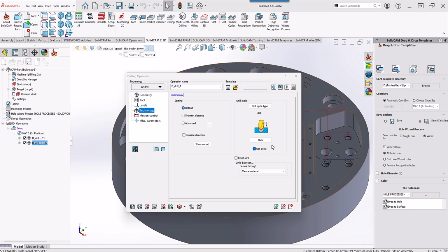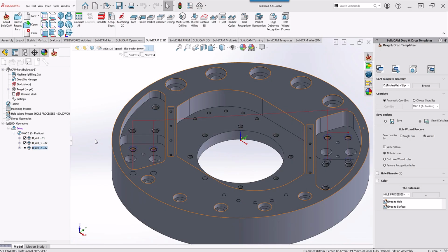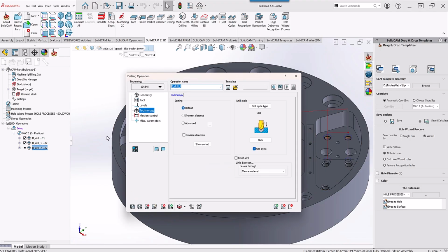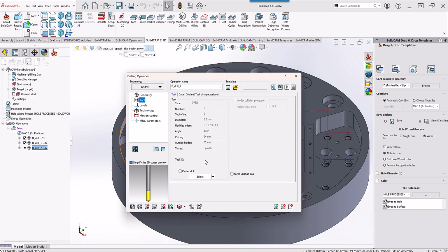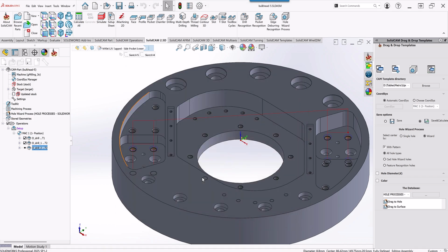In this recording, in our series of drilling operations, we'll be going through our tap cycle. Now that we've created our hole already with our pre-tap hole, which was an 8.8 millimeter hole, we're going to do a new operation by simply going to save and copy and creating a new operation again with the previous geometry. And this time, when we go to the tool, we're going to select the tool that is a tap.